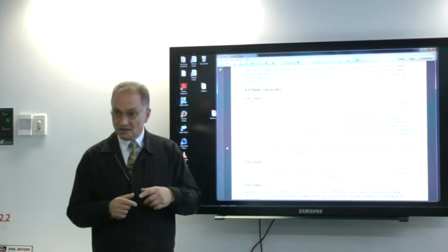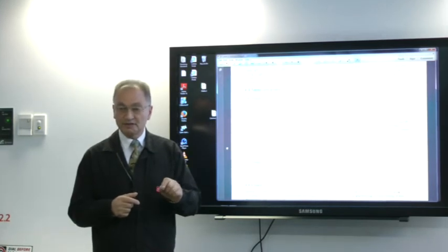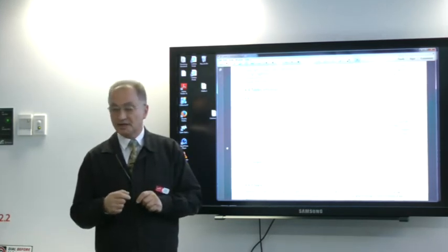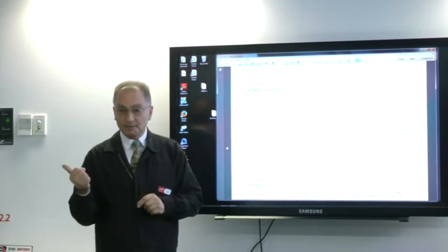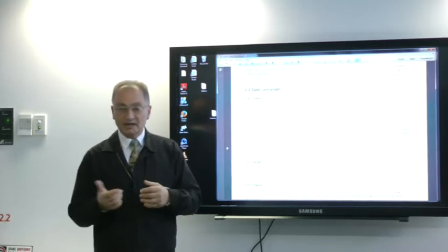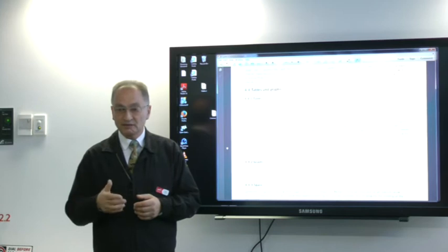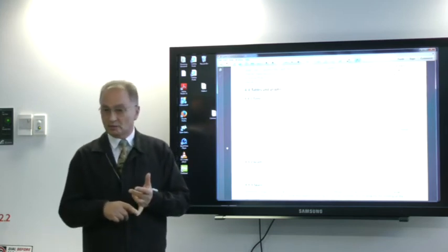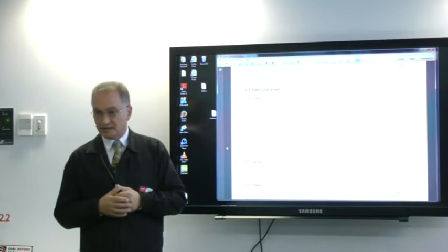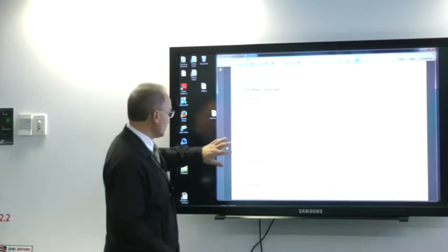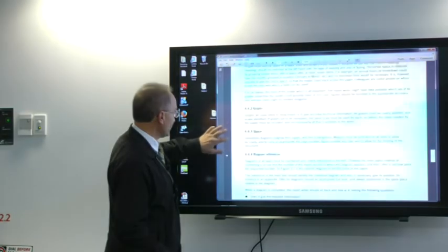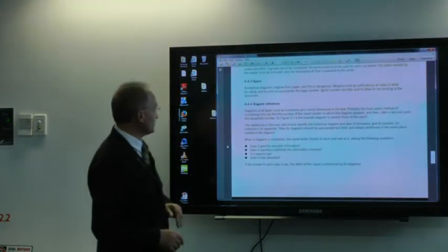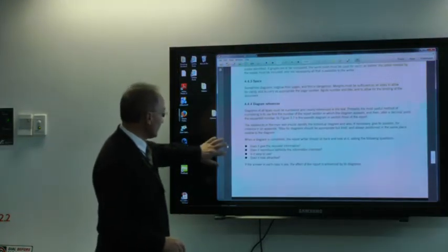should cross-reference. So in your calculations, if you're referring to a table from an Australian standard, don't just say refer appendix, because the reader might have to flick through 20 pages looking for it. So say things such as Appendix A, Table 3, or something to that effect. That way it's clear. It's all about clarity. It's all about encouraging the reader to take note of things that are important, and referencing of diagrams and that